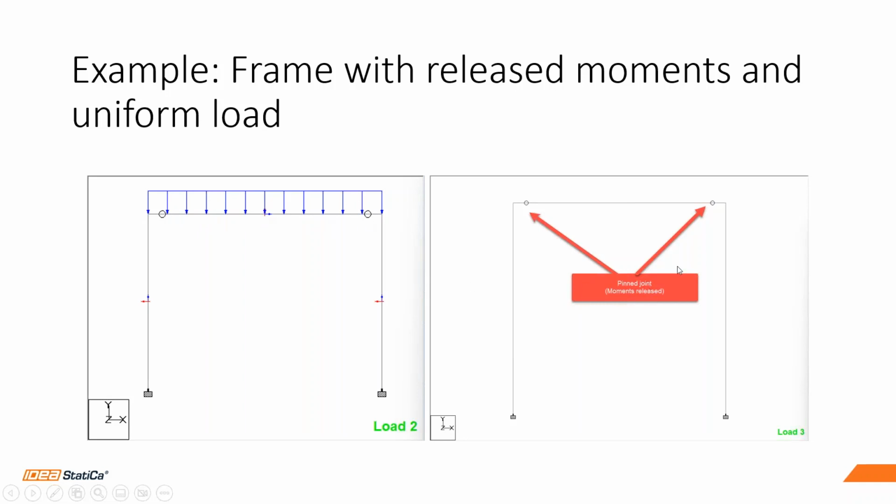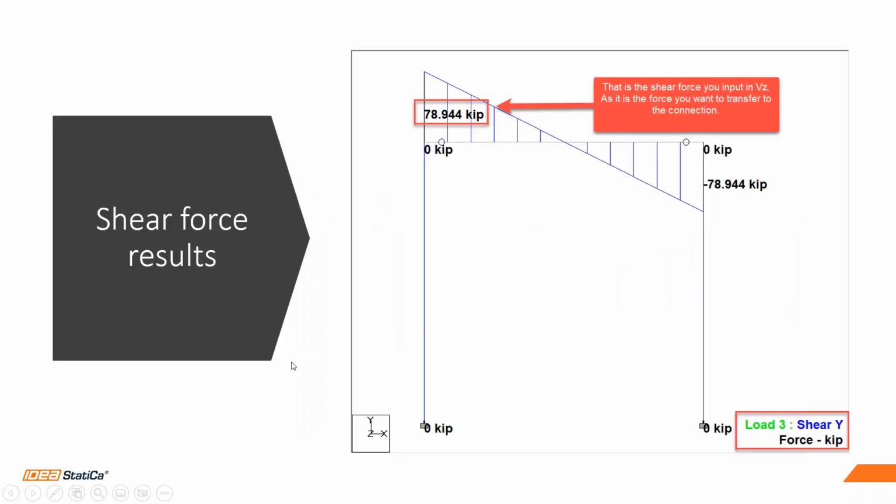Moments are released, and once you look at the shear force results, this is the shear force diagram you get. That is the shear force you input in IDEA StatiCa for loading your connection. Let's say you want to analyze a connection from this beam to this column. This is the value you will input there, because this is the end force of this member.